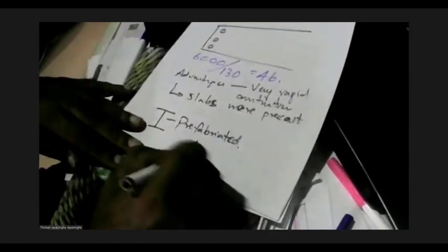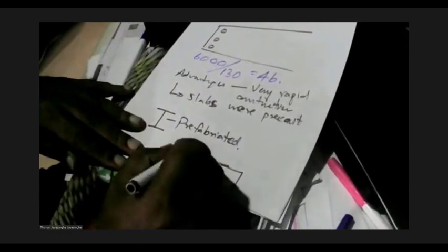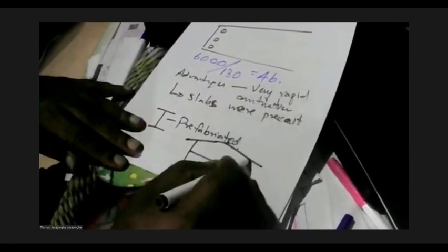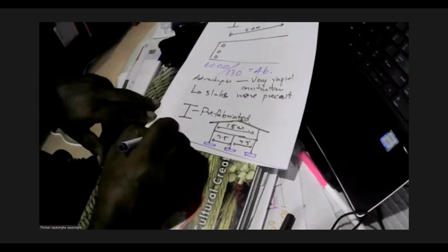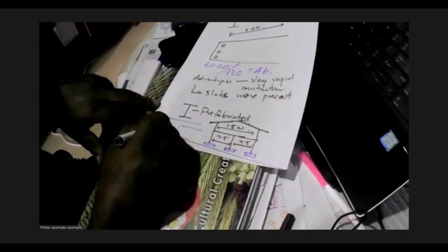So when you have a portal frame, we need a trick again. So here we used 7.5 meters and had a prop at the ground level. Here we had 15 meters. So we had clear spacing of 50 meters in the upper floor. In the ground floor we had a column. So then the foundations also, we went for something like an inverted cellular raft type.